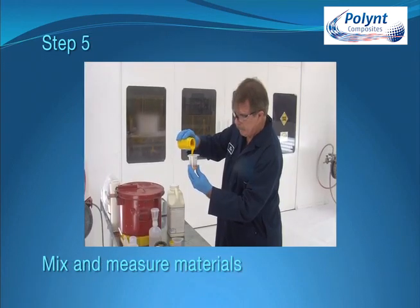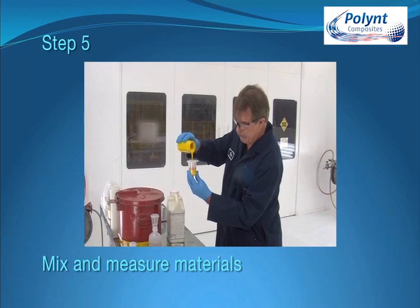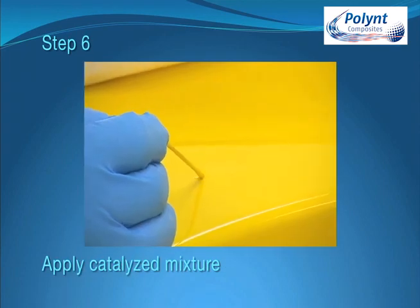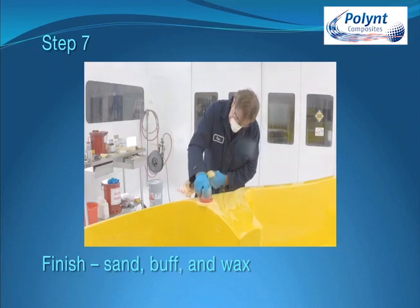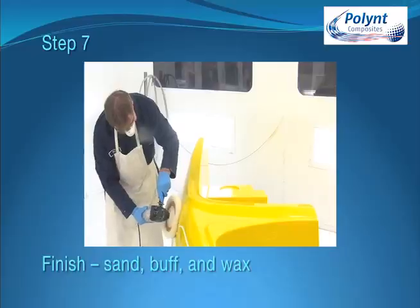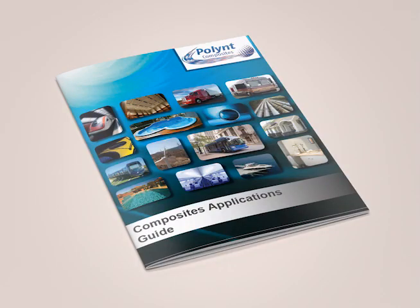Step 5. Mix and measure the materials. Step 6. Apply the catalysed mixture. Step 7. Finish, sand, buff and wax. If you would like more information about repairing gel coat, our patching section in the application guide includes these procedures: putty patching, gel coat and lamination patching, helpful hints and troubleshooting.